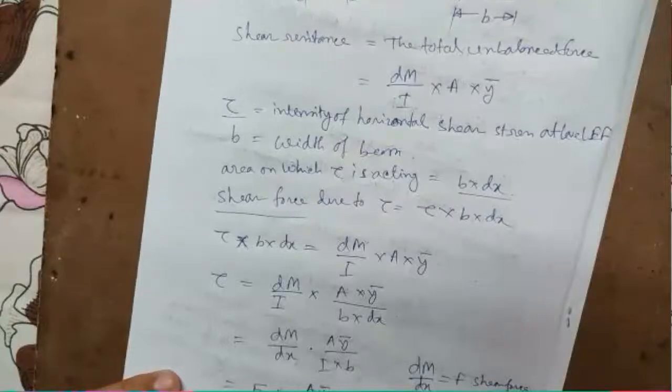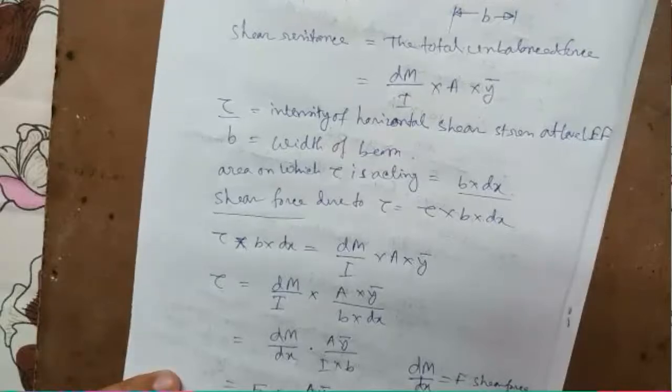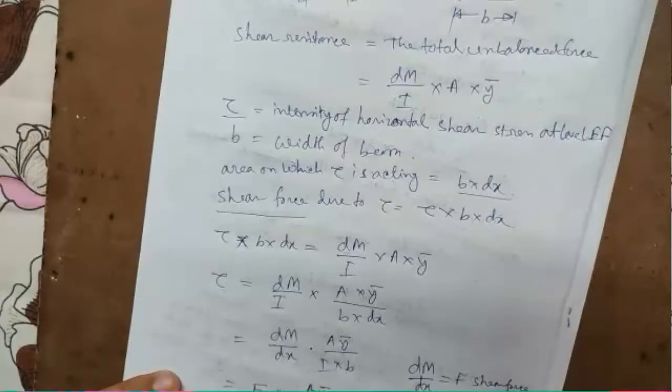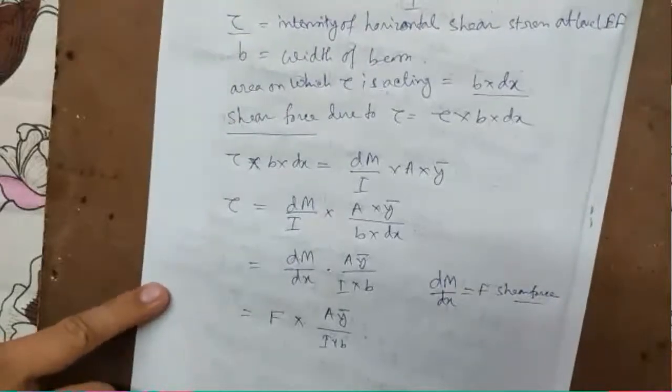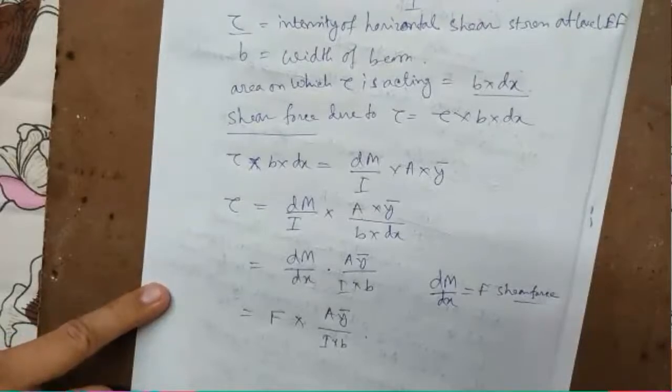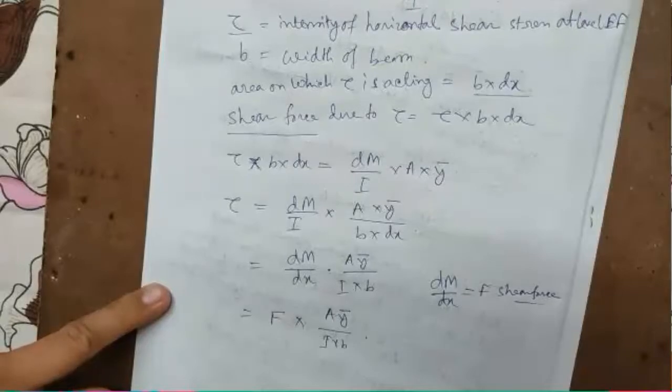Initially, the shear stresses were calculated on the vertical planes. If you remember, while solving problems on shear force and bending moment diagrams, we took only vertical forces, and due to the vertical shear force we drew the diagram. But as we can see, due to this bending stress, shear stress also occurs in the horizontal plane, and that expression is given by what we have just derived.